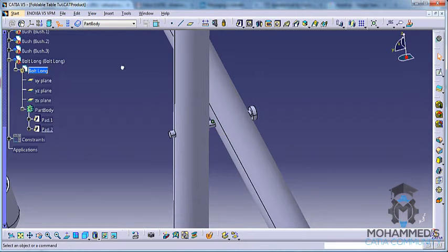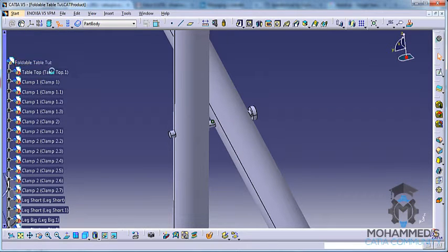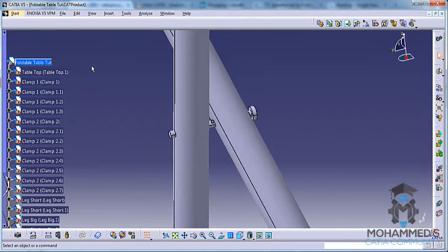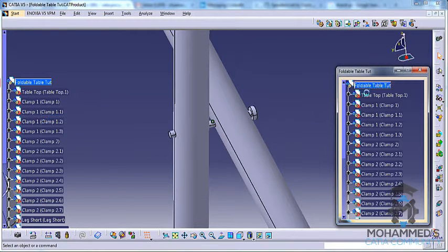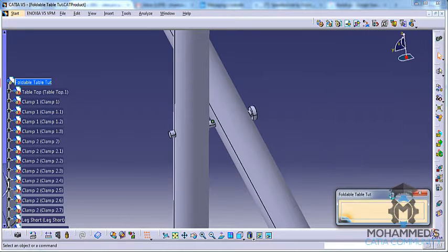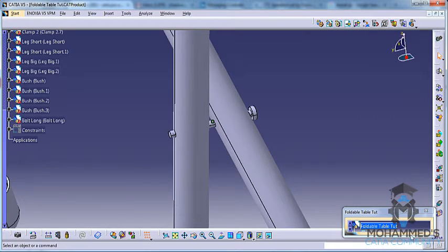What you can do here is again go for the product, double click on the product. If every time you have to move upwards like this and double click on the product, and if it's tedious for you, you can open a subtree and just pull it down and keep it here, so that every time you need to switch back to the product, you can double click from here. You don't need to scroll up. That's just a simple tip here.